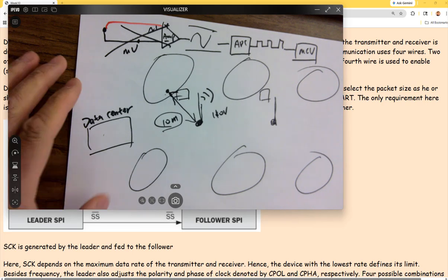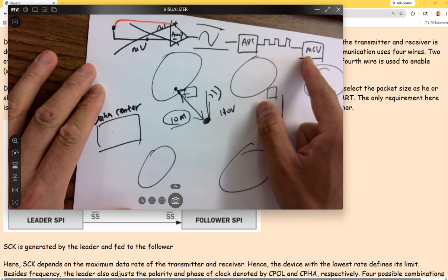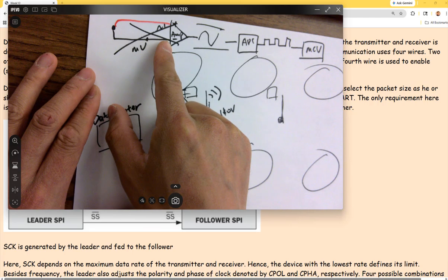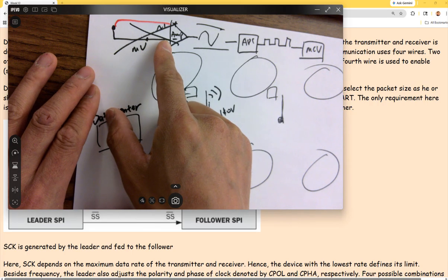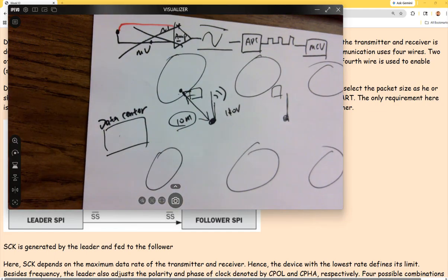Okay? So this is not a good option because you have to customize everything and make a PCB out of it. And there are other sensor modules which are built into a little tiny chip. Okay, so that chip is basically a temperature sensor. It is able to sense the analog temperature data, and then directly amplify and digitize it.